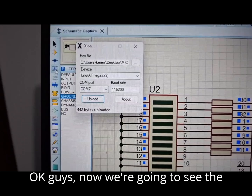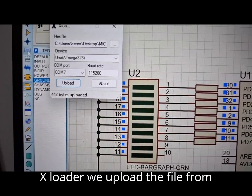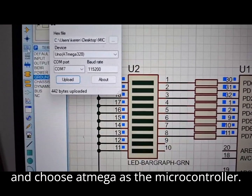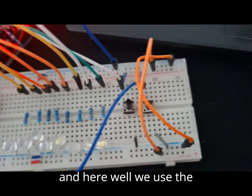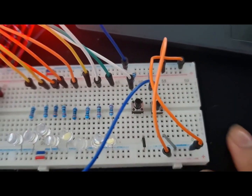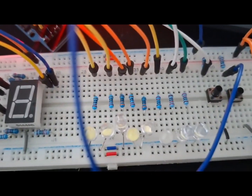Okay, guys, now we're gonna see the exciting part. Well, first, in the Xloader, we upload the file from practice number 2, we select the USB port, and choose Atmega as the microcontroller, okay? Like we did in the last practice. And here, we use the proto and add 2 push buttons, and we also use 8 LEDs.